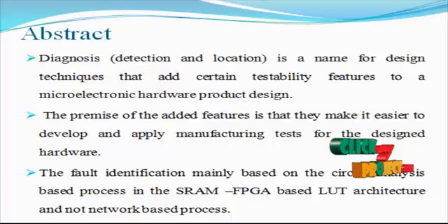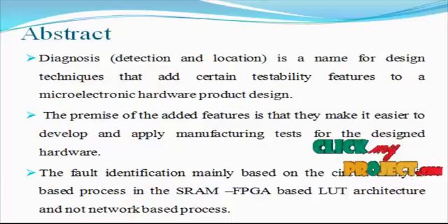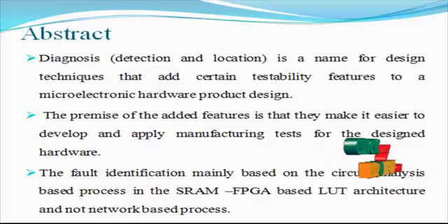The proposed method detects all possible stuck-at and bridging faults of all nets in a single configuration. Fault detection requires 1 plus log 2 of k test configurations for multiple stuck-at faults, and 2 plus log 2 of k additional test configurations to locate the pairwise bridging faults. In the fault location process following detection, multiple faults are hierarchically identified using the walking one test and the adaptive approach of the interconnect SRAM structures.